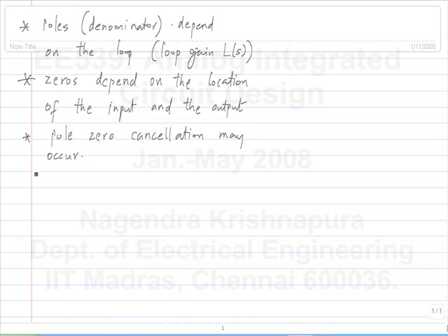So these are properties of feedback system. Now this also can be used in design. So if you find that your poles are at too low frequencies or they are imaginary and they are ringing, I mean you have ringing in the response, you will have to change the loop in some way. Okay, that's a prerequisite. Or let's say you want to modify the transfer function by changing the zeros, then you can try to look for other locations where you can inject the signal or where you can take the signal out of and then manipulate the zeros of the transfer function. Okay.